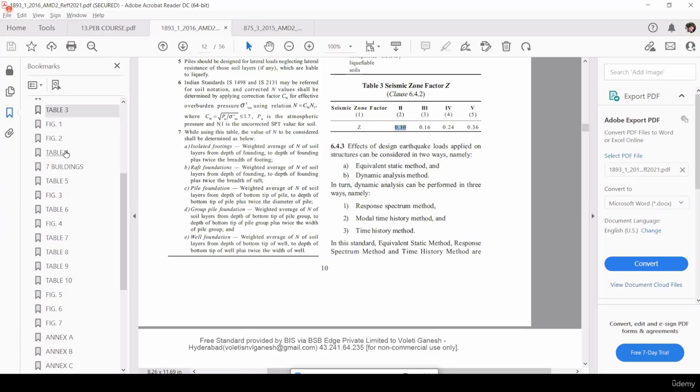So for steel MRF building, steel moment resisting frames, this is the formula which is applicable in the fundamental time period calculation. TA is nothing but 0.085 h to the power of 0.75. I have provided the formula here. What is h? H is nothing but the height of the building. What is the height of the building here? 6 meters you can see. I have assumed the height of the building is 6 meters.